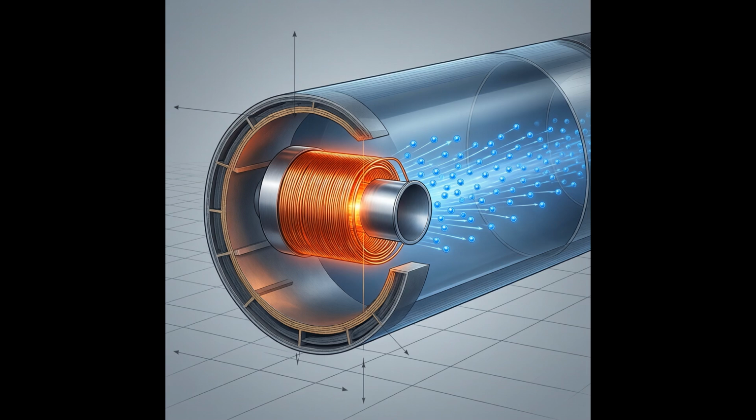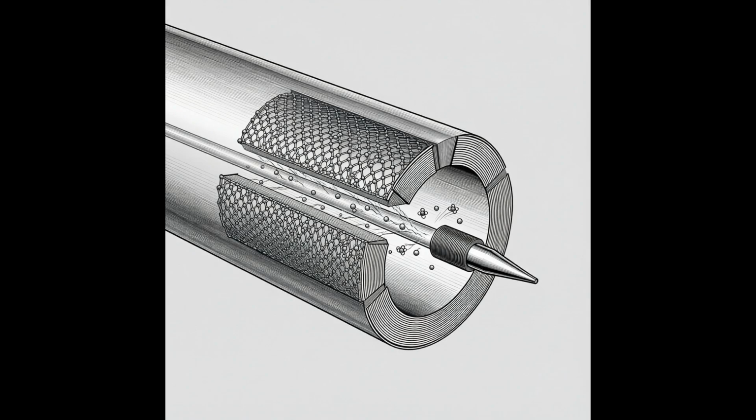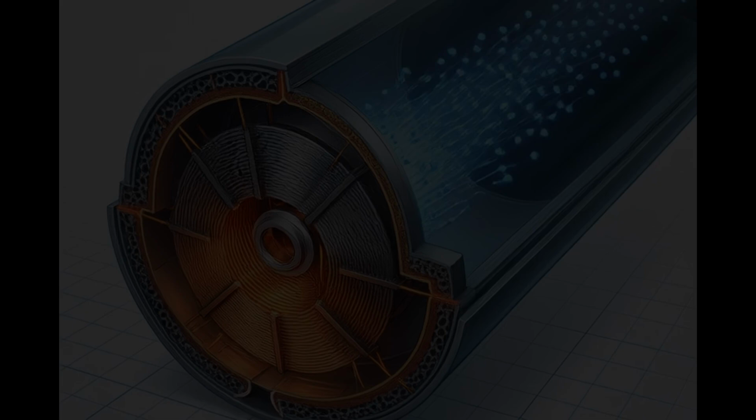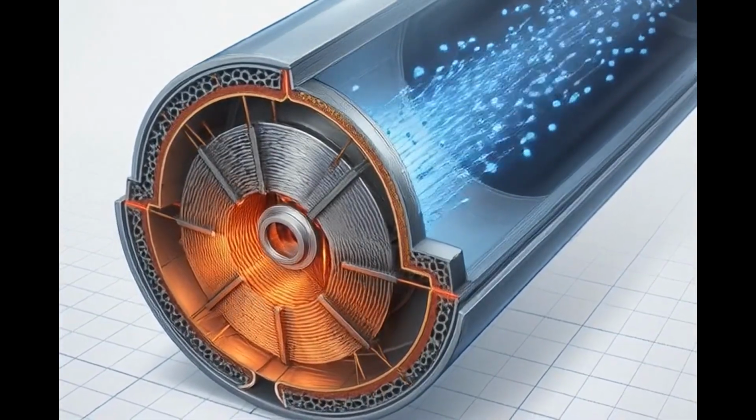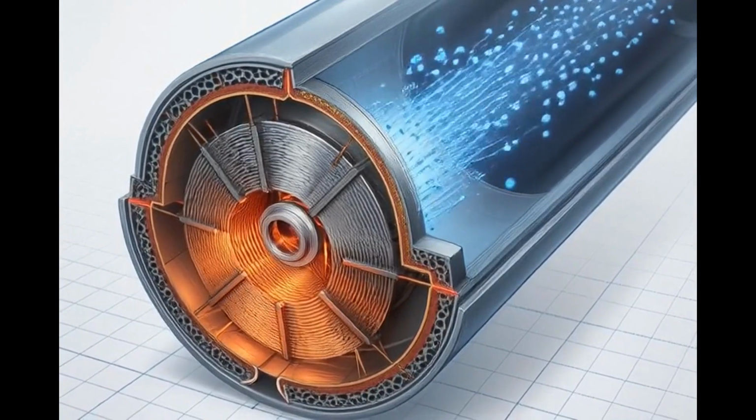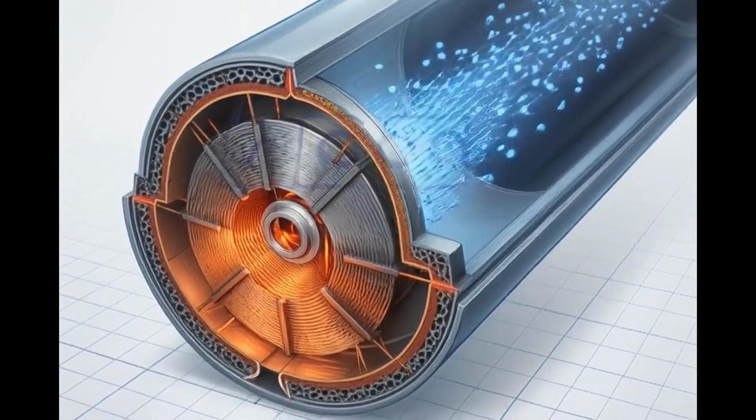To create an image on a cathode ray tube display, we must first generate a controlled stream of freed electrons. This process begins at the electron gun assembly through thermionic emission, where heat liberates charge carriers from a solid surface. The cathode is constructed from materials with low work functions, such as barium oxide coated on a nickel sleeve, which allows electrons to escape when heated.